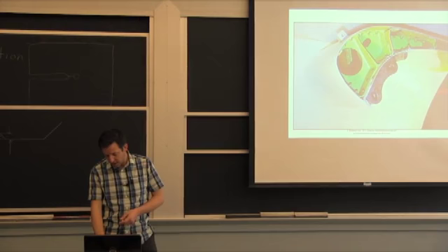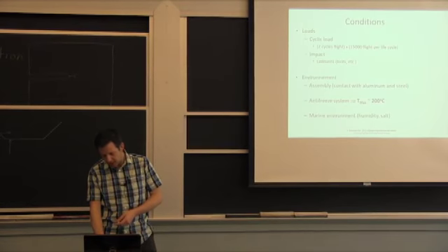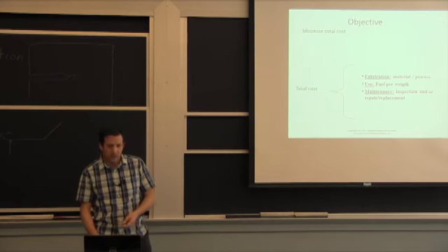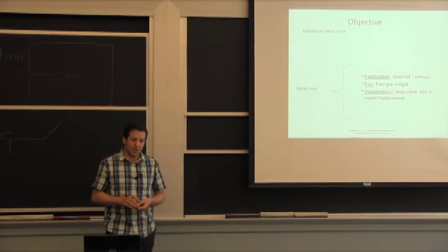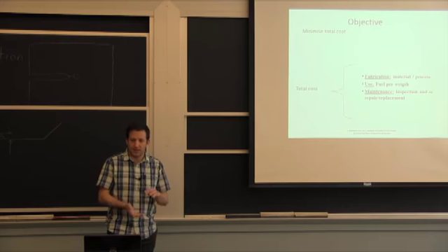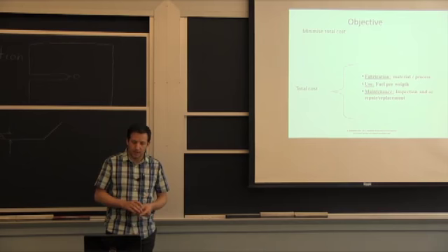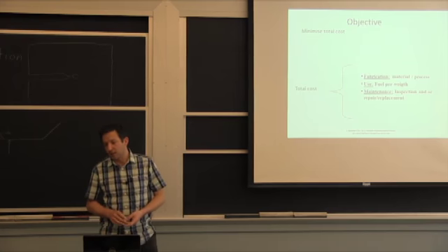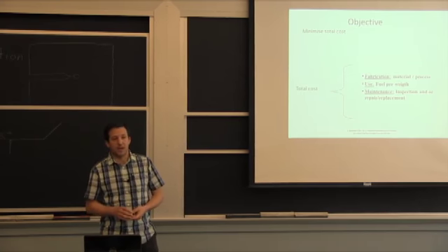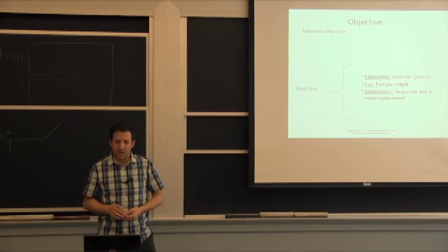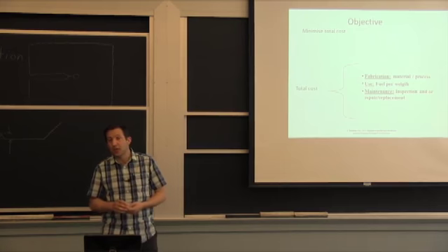But in this particular case, what I was looking at is essentially the choice between using different titanium alloys, but also using a wrought product that was a thick plate machined down to form the rib, as opposed to using more of a casting process, investment casting, where you form the part out of wax, you make a ceramic mold with it, and then you almost cast it to shape.